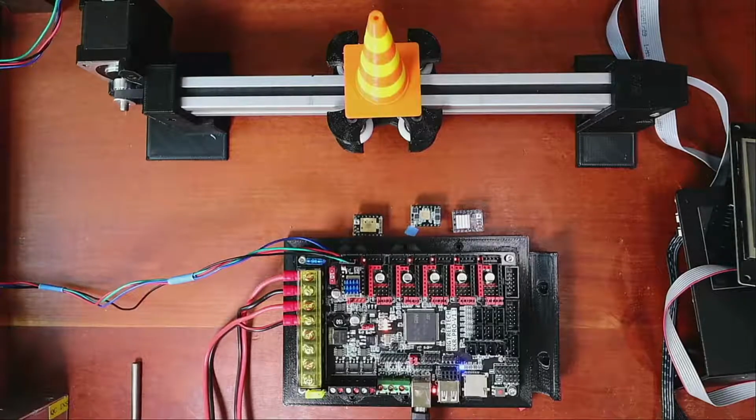You're still getting the no printer attached, David. Inside your firmware, does it say that your serial port is 1? And then on your TFT display, does it say under settings what speed you're actually communicating with your board?